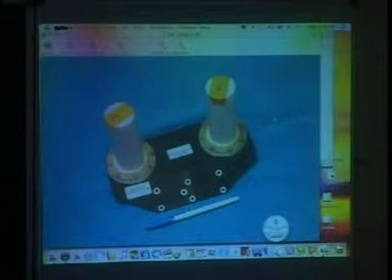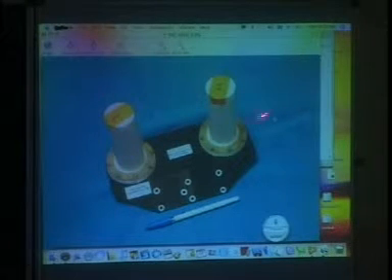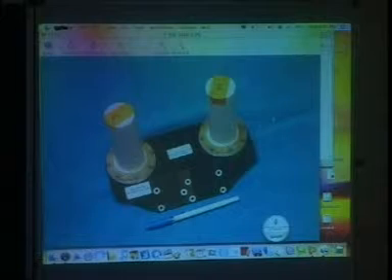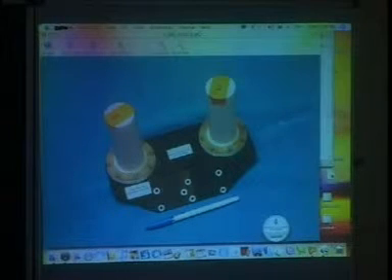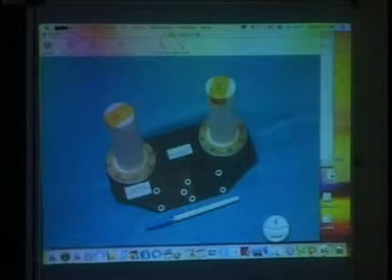So this is also the same thing, with the boom and without the boom. See, one is downlink and one is for uplink. Here the S-band size is similar, because they are all very close to 2 to 2.5. Sizes are not much different. Whereas in C-band the element was very, very small. And that too, uplink is 6.4 gigahertz, downlink is 4.2. So the sizes are much different, as we saw earlier in the morning.